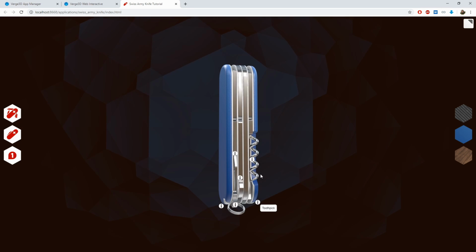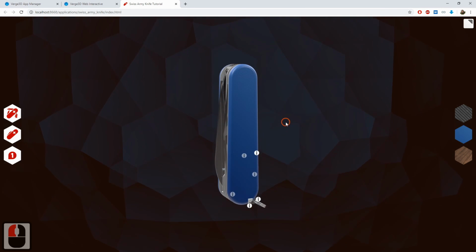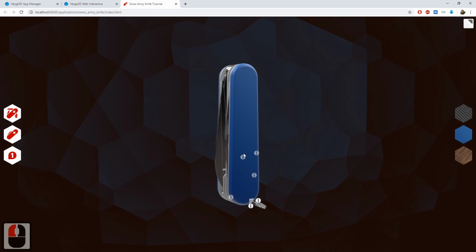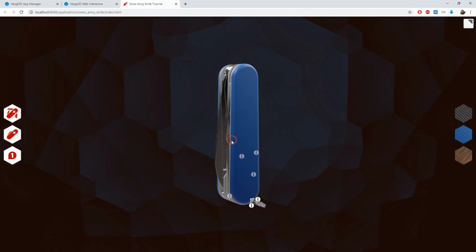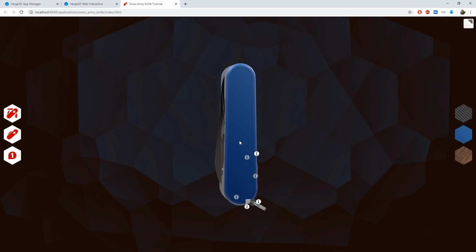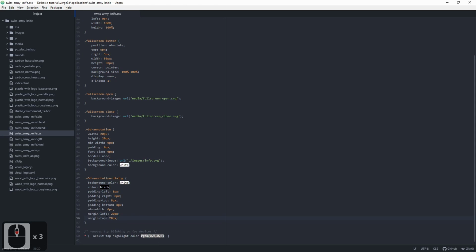There is one small issue left though. The issue is that the obscured annotations are not that much different from the visible ones. This can be easily fixed by using another reserved CSS class, namely .v3d-annotation-transparent.